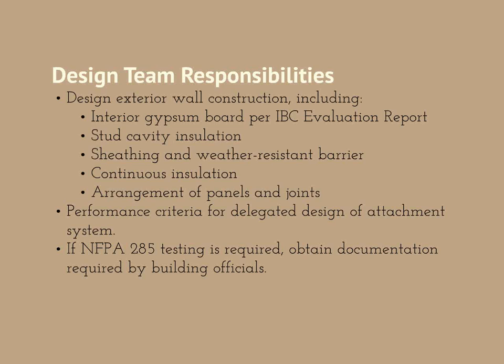Go ahead. This CI notation means that the insulation must be installed in a manner that is continuous and uninterrupted by framing members or other construction elements that would reduce the thermal resistance of the insulation when installed in the construction. Now, does that sound like a Z-girt to you? It certainly does. So, you know, the whole point of doing the continuous insulation is to isolate the metal framing, especially the stud framing, from the exterior, so that we don't have the thermal bridges between the interior and exterior.